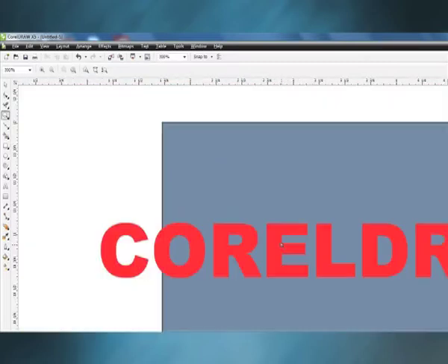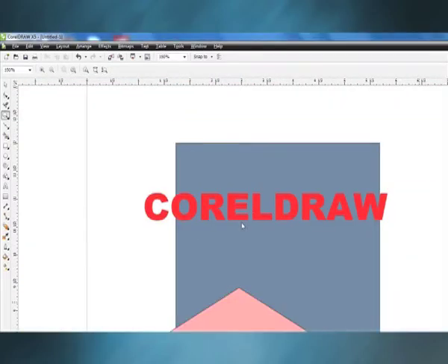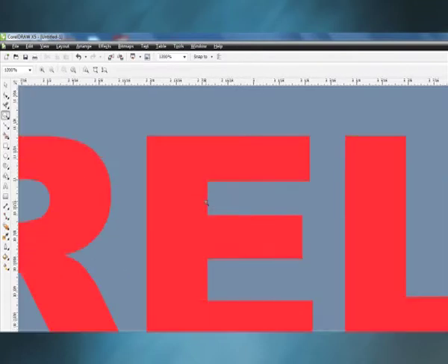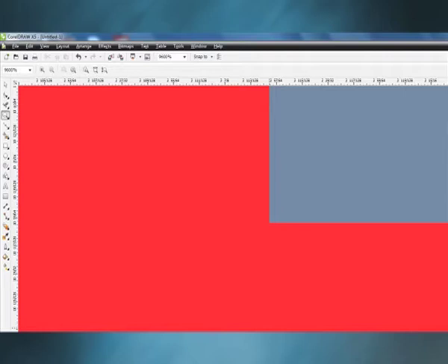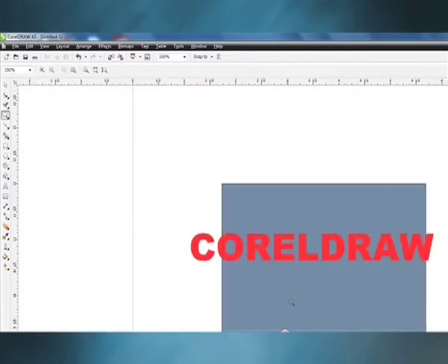If you press F3, then zoom level decreases one level on each click of the mouse. By pressing F4, you will switch to all objects, either available in one page or in the whole pasteboard. After pressing F9, you will be switched to full preview mode.